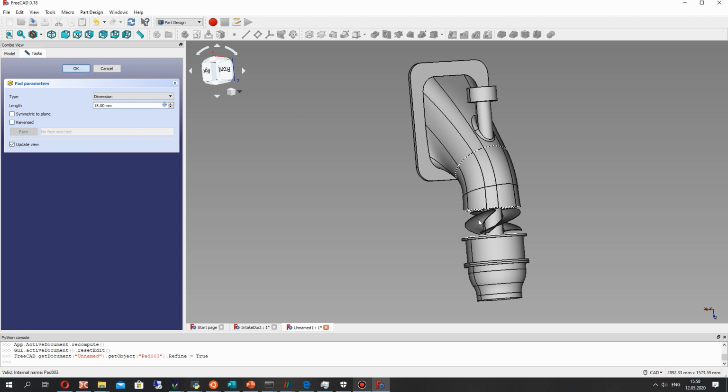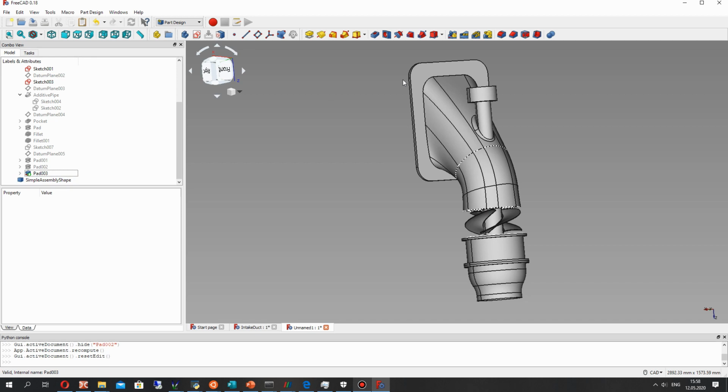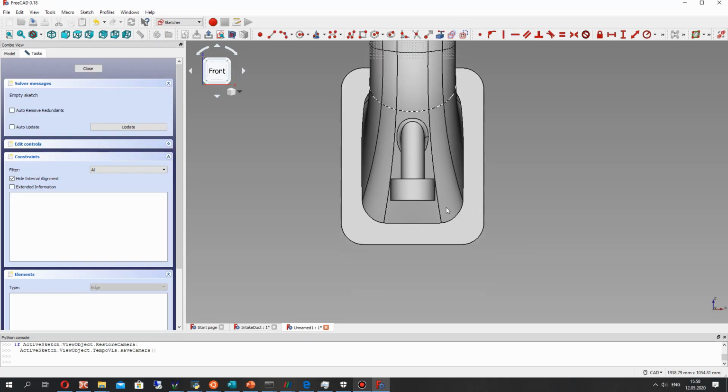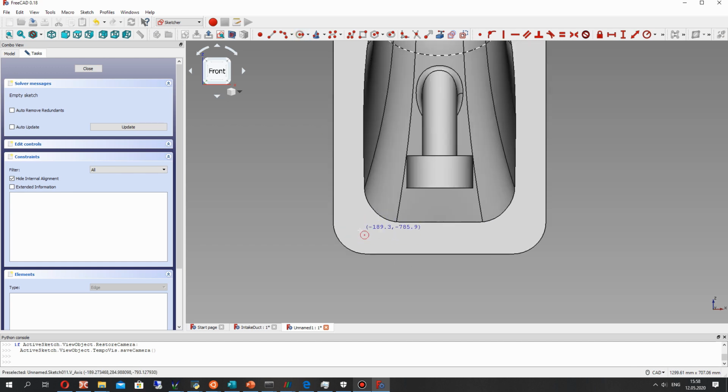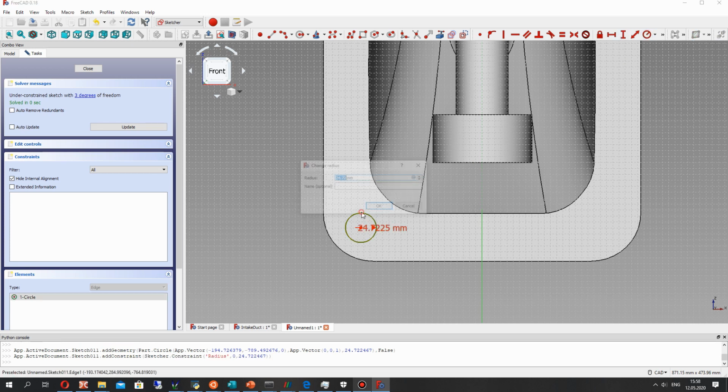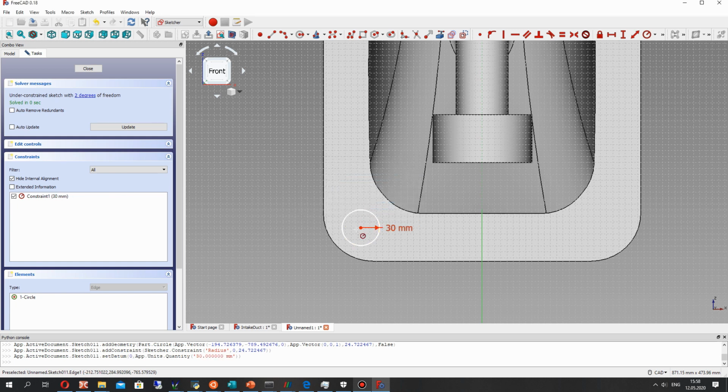Oh, now it doesn't have the fault, and it works good. So let's create the holes on the platform. It will be 4 holes with diameter. Let's make it 20 millimeters for this case.